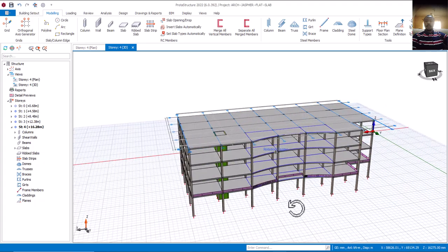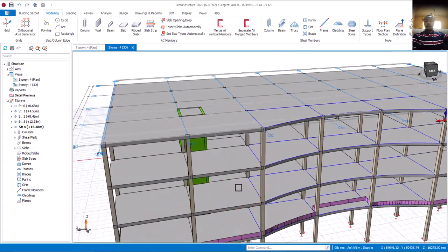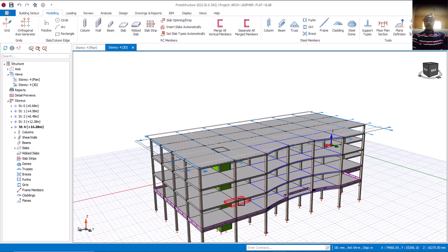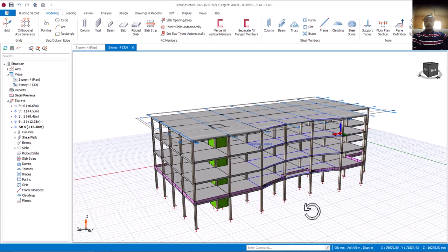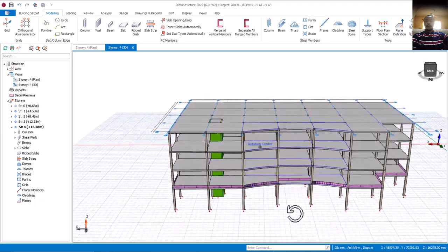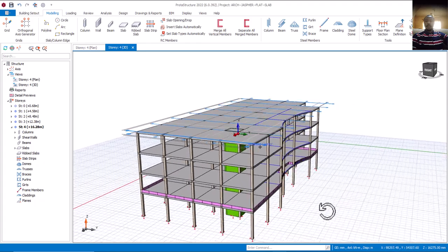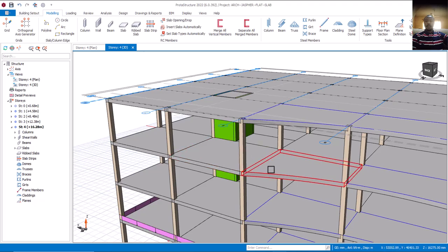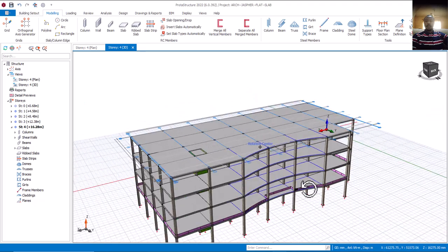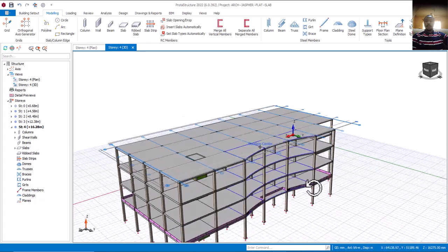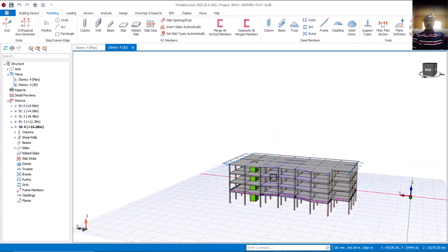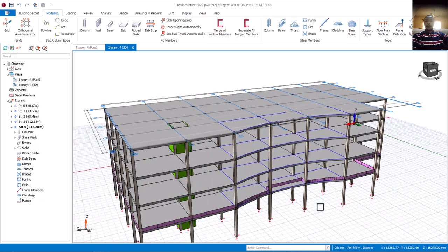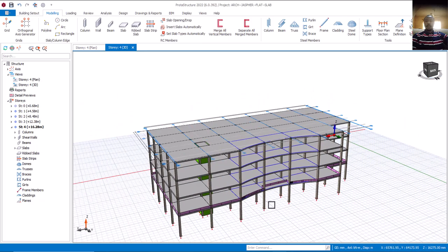Nothing like changing of your column, because we know that slabs are not meant to carry columns. What is meant to carry columns is your beam. In this case that we don't have any beam, automatically you know that you cannot be positioning your column on a slab. The essence of that is because of punching. I will explain that as part of this video.